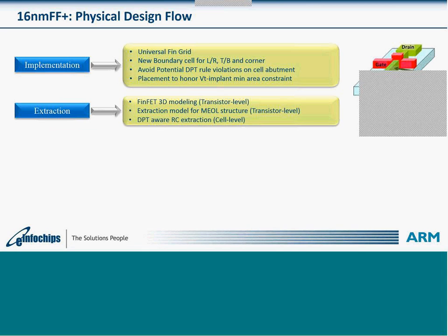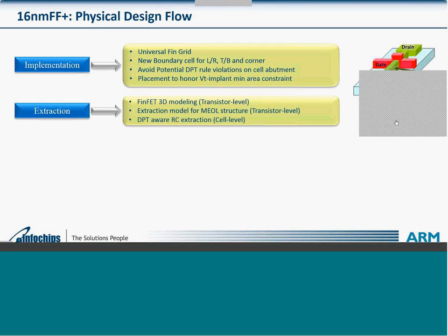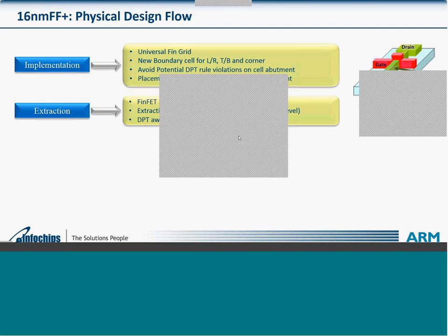Next challenge comes while doing extraction. Is 3D modeling required? Because FinFET is basically 3D, and with the introduction of FinFET, it's very difficult to do this 3D modeling of fins. For the MEOL structure, which is basically middle end of line, which was not present in earlier technologies, early technologies only consisted of back end of line and front end of line. Now there are also additional layers, which are middle end of line, which connect the base layer to M1.